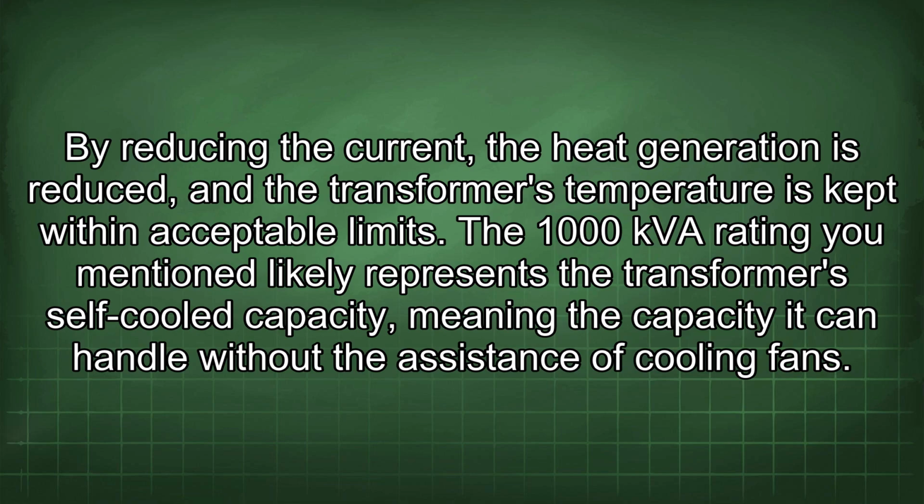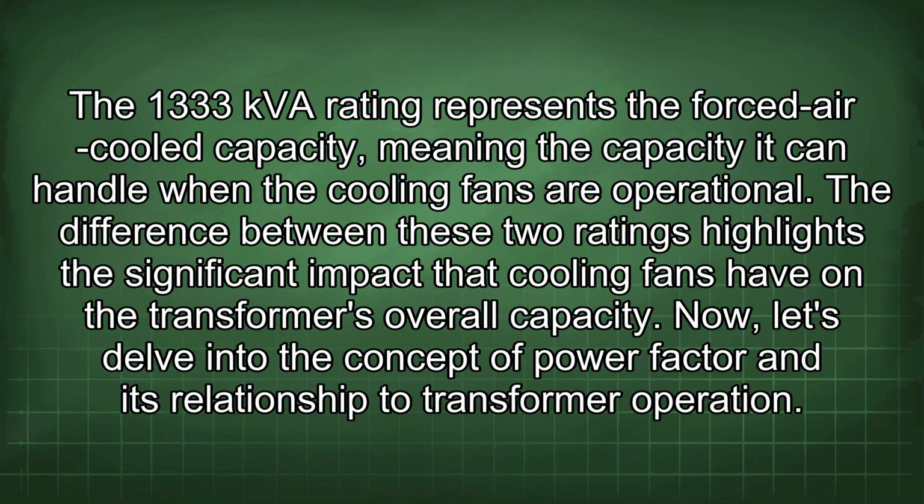The 1000 kVA rating you mentioned likely represents the transformer's self-cooled capacity, meaning the capacity it can handle without the assistance of cooling fans. The 1333 kVA rating represents the forced air-cooled capacity, meaning the capacity it can handle when the cooling fans are operational. The difference between these two ratings highlights the significant impact that cooling fans have on the transformer's overall capacity.